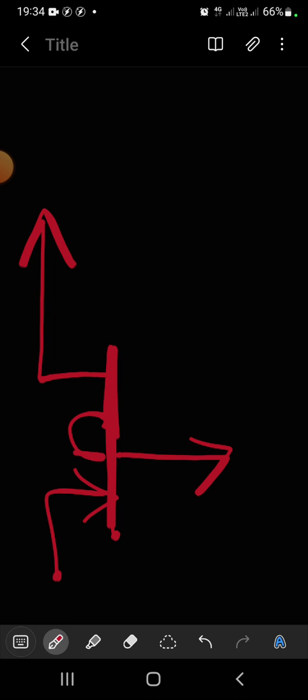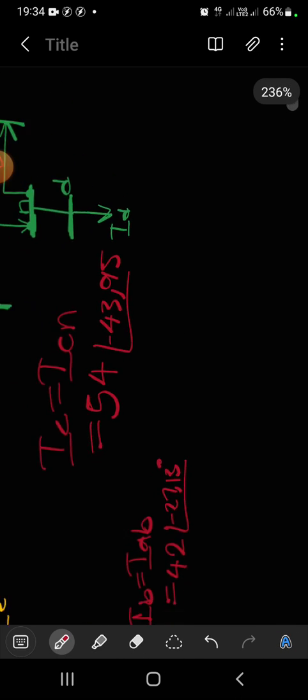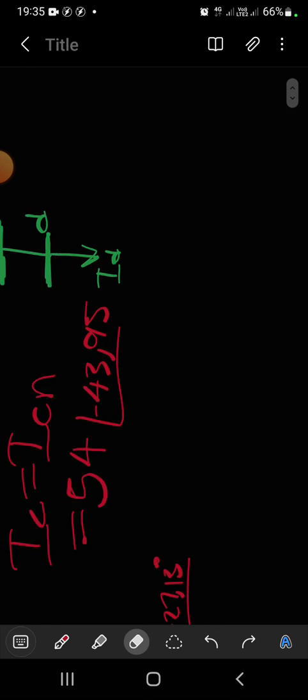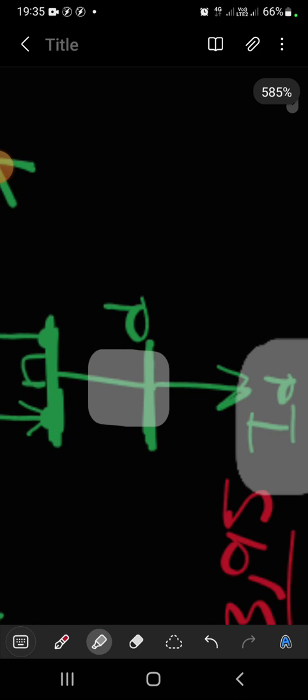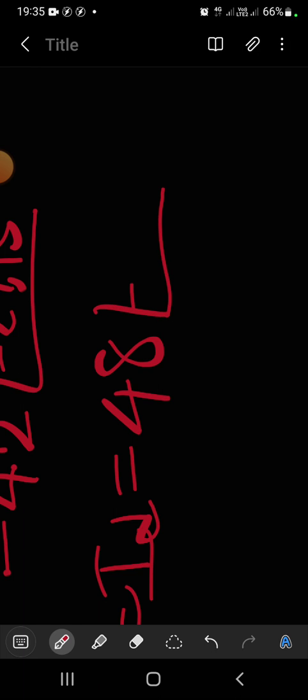IAN is approaching bus bar N, right? And then IDN is leaving, and ICN is also leaving the point, meaning IAN is equal to the sum of these two, right? Let's see, did we calculate IDN? No, we didn't. However, this current here is in series with IDN, correct? Meaning your IDN is equal to ID, and that is 48, comma minus 35, comma 9.